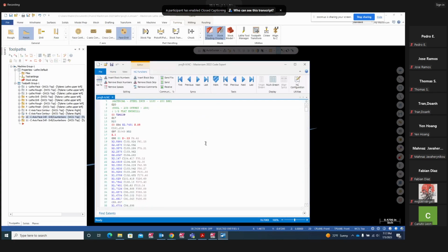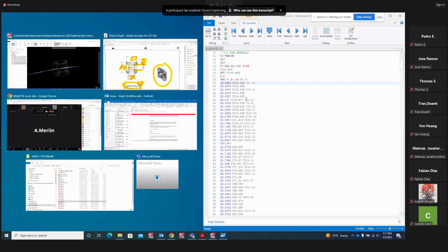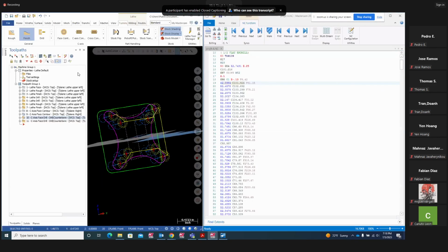Look at this. It's a combination of your X and C axis. Look at this, how you see the axis is turning, your spindle. Each block is 101.92, 102.692. That's degrees. So it turned into such a small increment of degrees that it becomes a straight line with C and X axis, which cuts this part right here.